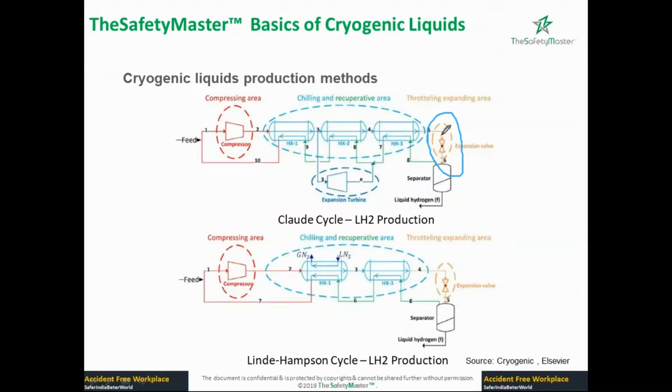It's an isenthalpic process, which means enthalpy remains the same, but it's an irreversible process. So the vapor and liquid both will form at the exit.